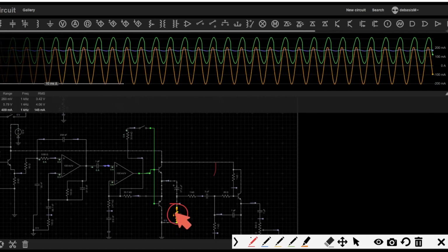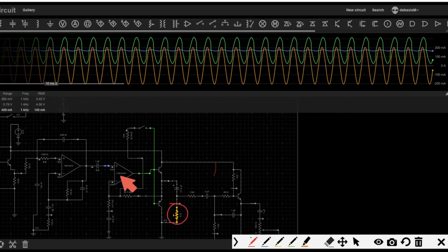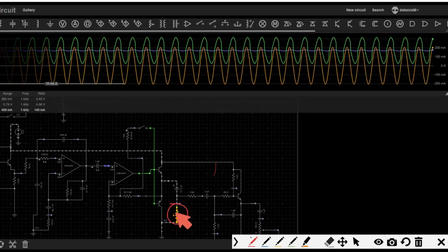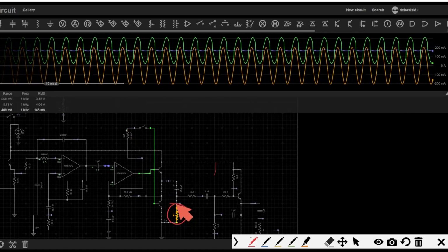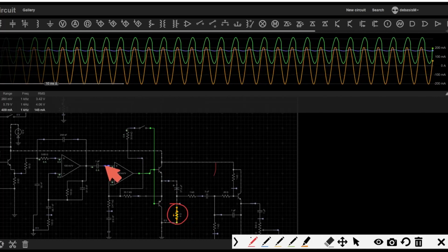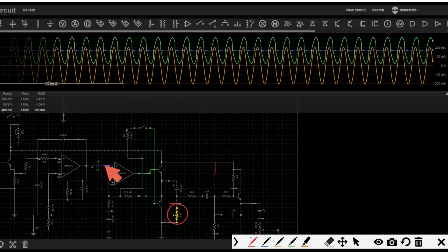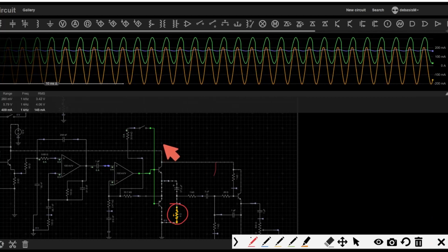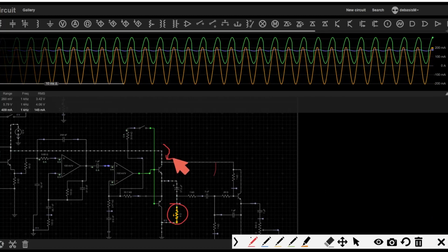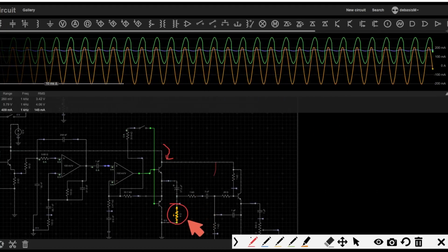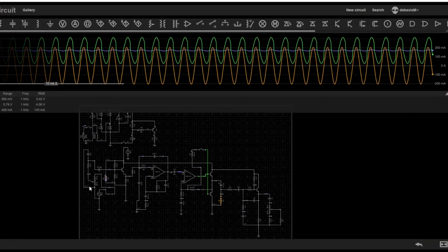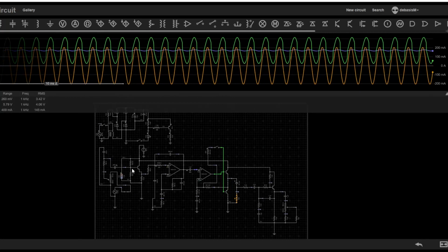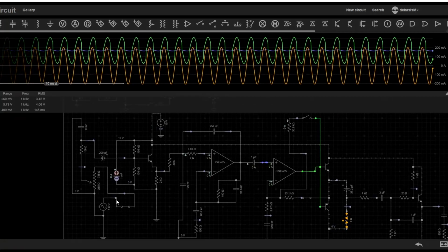Now what has happened after doing all these things? The voltage across the speaker is the same as the voltage here in the op amp, so what we have amplified is actually the current. You see the large amount of current flowing here. In this orange line you have 200 milliamp of current flow. Let's see how much current we are actually drawing from the audio pin itself.